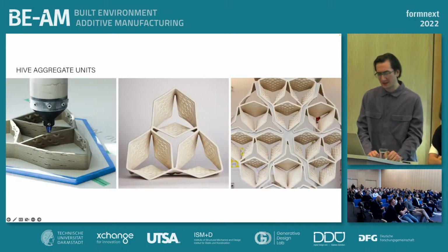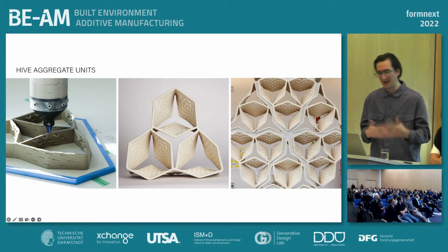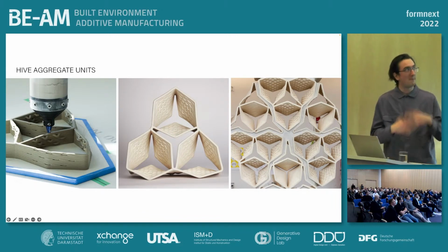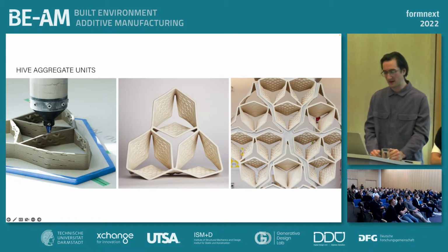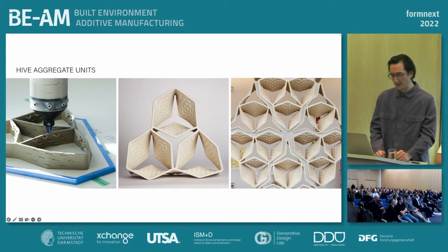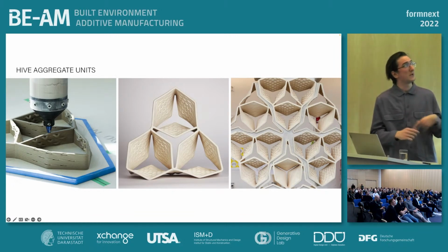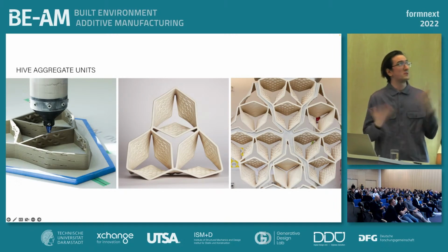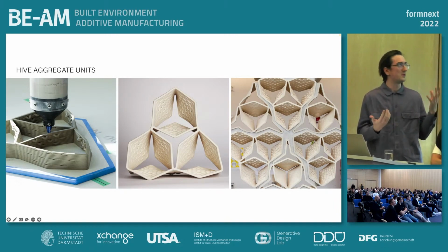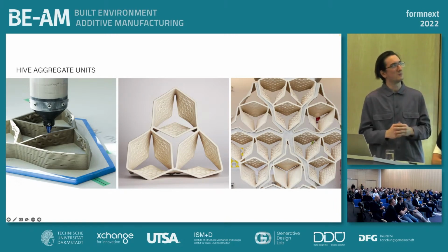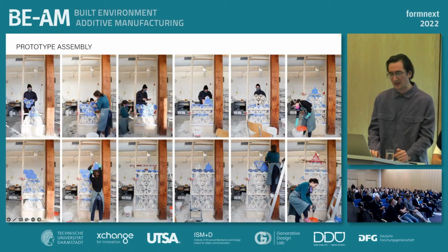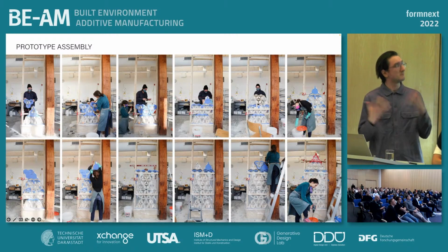So the commission was initially conceived of as 1,600 masonry units. It formed single apertures. This was very inefficient in terms of time and labor when addressing this idea of a masonry unit as a 3D printed ceramic fabrication process. So we worked with turning the original intent into a continuous print path that reduced this very large number of 1,600 units down to a scale that was more feasible, 175, while keeping the same overall scale of the project.